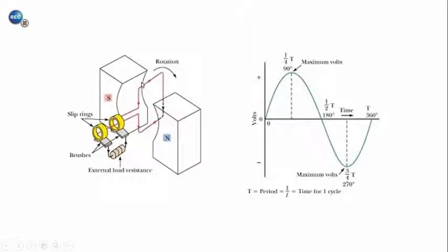And so here, when this coil rotates, this top part of the conductor sometimes passes down through the magnetic field and sometimes passes up through the magnetic field. And so down versus up is going to correspond to either the electrons flowing in through that part of the conductor or out of the page through that part of the conductor. And what that results in is an alternating current.